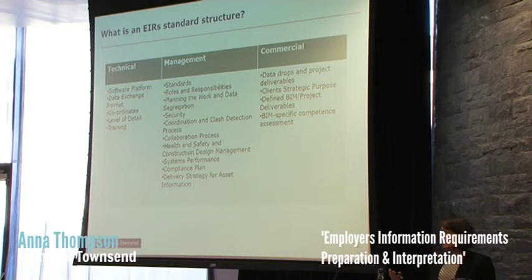So BIM, the building information model, is very much like Lego. It's made up of objects. And those objects can have intelligent data attached to them. That data is important to other project stakeholders, to the client, to the cost manager, to the contractor, to the project managers, to health and safety advisors. And so we need to think about what data needs to go into the model at which stage. So the level of detail that we're looking to see the model being developed to for each stage.